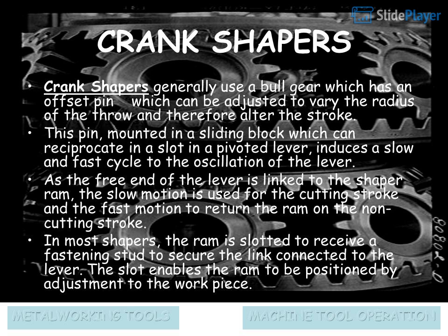As the free end of the lever is linked to the shaper ram, the slow motion is used for the cutting stroke and the fast motion to return the ram on the non-cutting stroke. In most shapers, the ram is slotted to receive a fastening stud to secure the link connected to the lever. The slot enables the ram to be positioned by adjustment to the workpiece.